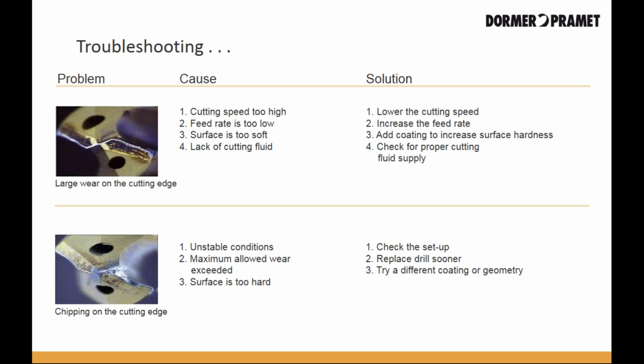Solutions: check your setup, replace the drill sooner. Always have a replacement plan where you're pulling that drill prior to the total failure of the drill. Try a different coating or try a different geometry.